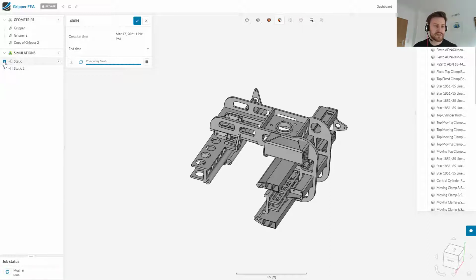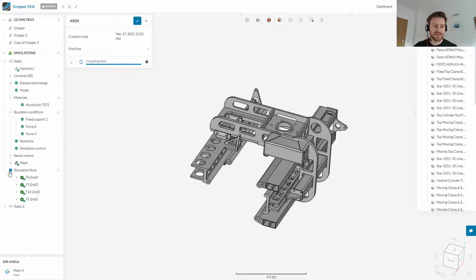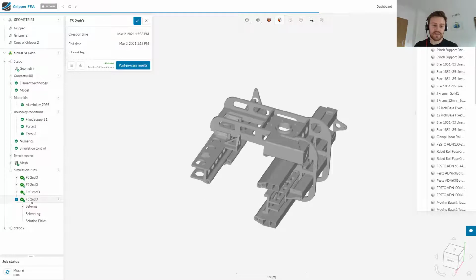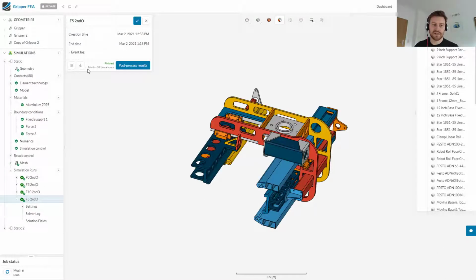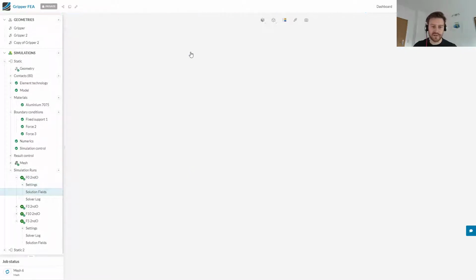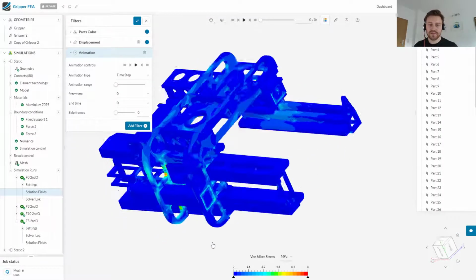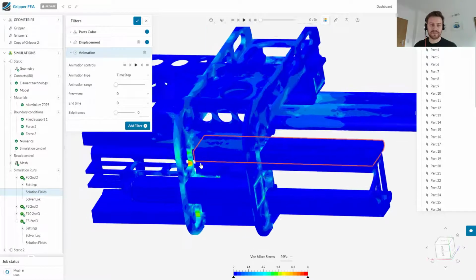So just going back to the original simulation for a moment, let's have a look at the runs that we ran previously. The one that I looked at with you was the standard mesh settings with a fineness of 5, and that took 16 minutes to run. Even with the coarsest mesh settings, we would still get meaningful results. It would have taken 3 minutes to run. We would have got meaningful results, and we would have still understood that that was the highest stress region of the component. We just wouldn't have had the same level of detail. And this result would have been obtained within 3 minutes.